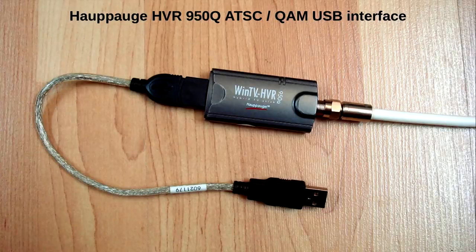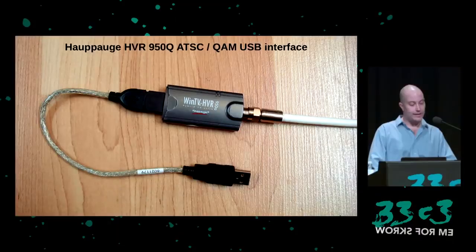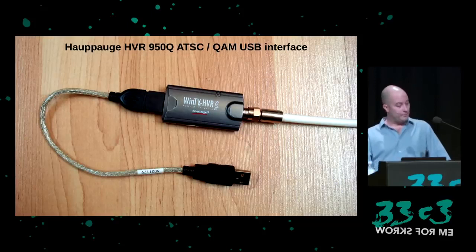For cable, there's a variety of adapters supporting QAM 256 demodulation. I used a USB HVR 950Q tuner. Unfortunately, tuning the out-of-band channel is generally not supported by off-the-shelf interfaces. Inside a cable box, it's handled within the integrated chipset, and for clear QAM consumer devices, such as USB interfaces, access to the out-of-band data isn't actually required, so they don't include it inside the hardware. This out-of-band data is used only for pay TV services.